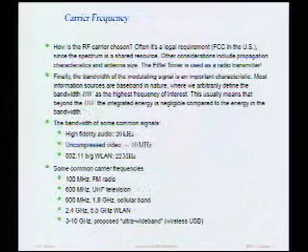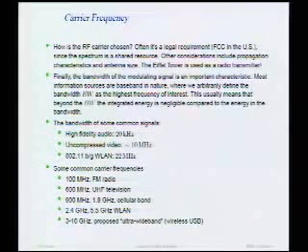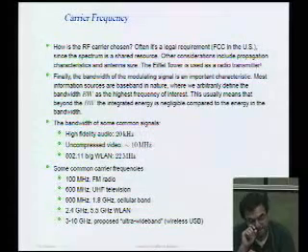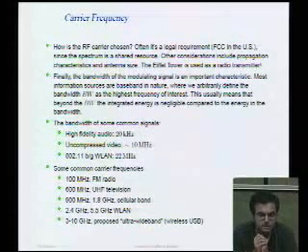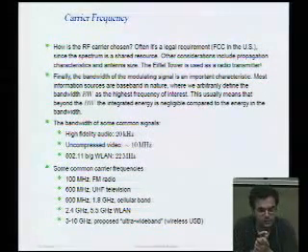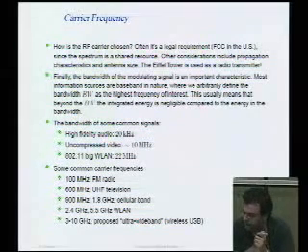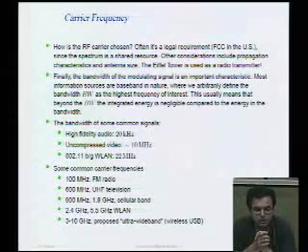So how do we choose the carrier frequency? Well, we already talked about the fact that using higher frequencies means we can make smaller antennas. Of course, if you go too high in frequency, your circuits won't work. So there's kind of an optimum frequency, if you like. But life isn't so simple. It's not just determined by technology. It's also a legal thing.